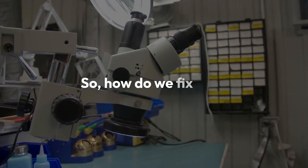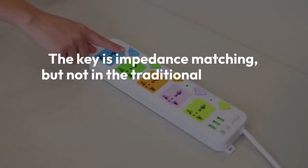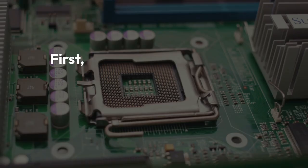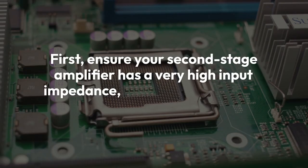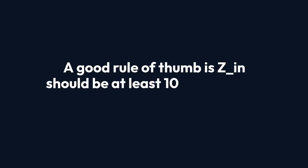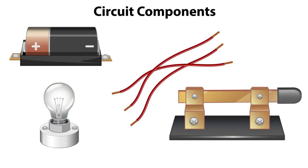So, how do we fix this? The key is impedance matching. But not in the traditional sense for power. Here, we want minimal loading. First, ensure your second stage amplifier has a very high input impedance. Much higher than the op-amp's output impedance. A good rule of thumb is Z_in should be at least 10 times Z_out. Even better, make it 100 times. This way, most of the voltage drops across Z_in.